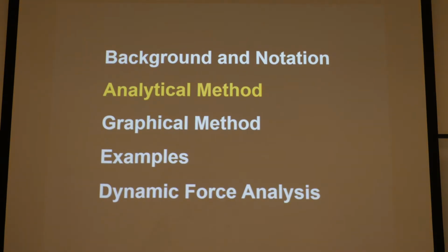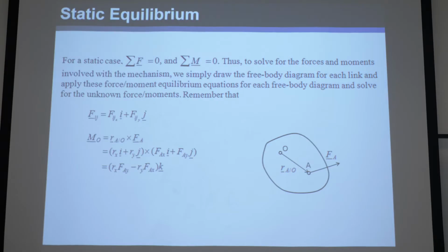All right, so let's do a little bit about the analytical method. So there's an analytical way that you can take these forces into account. Okay, so this is still hopefully a review for most of you. So anytime you have a body or a link, you can take it out of the mechanism and just kind of draw a free body diagram on it, where you show all the forces acting on the body, and it's great if you know where those forces are acting on the body, of course, and then all the moments or couples or pure torques acting on the body, okay?